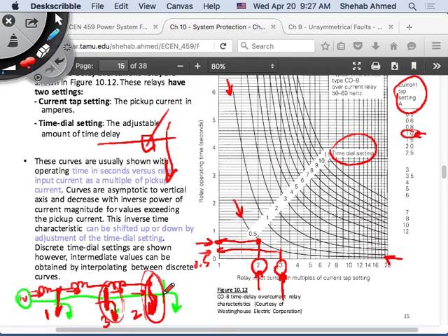If the fault happens at 2, and the relay that is protecting bus 2 fails, right? If it fails, what do you want to happen? What would you like to see? I would like to see that the relay at bus 3 will disconnect, right? If the relay that's protecting the fault at bus 2 fails, does not operate, then I would like to make sure the relay that's protecting this bus picks up the slack. It's a backup for the other relay.